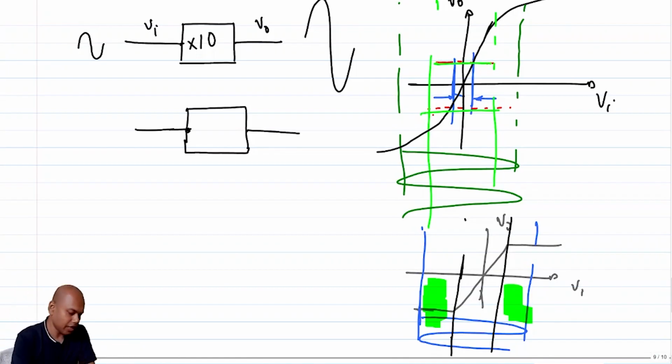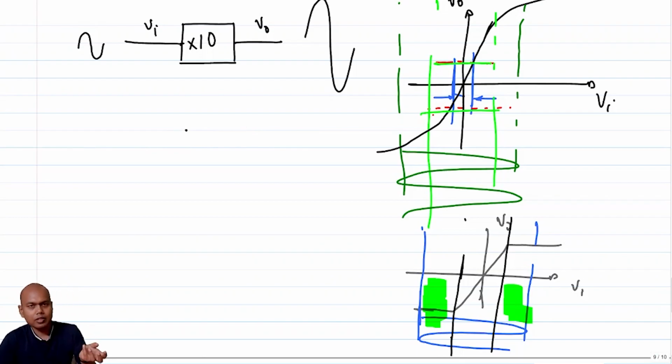Now clipping is an extreme phenomenon, right? You might not necessarily wait for clipping to understand that distortion has started to dominate. In most analog or RF circuits, the effect of distortion starts even before you start seeing actual clipping.